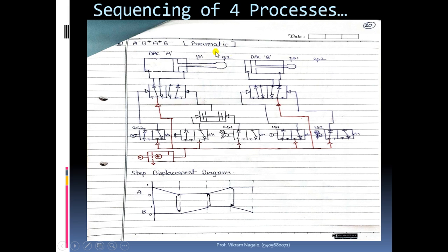That means the limit switches placed at 1s2 and 2s1 will be in press condition. Those will be initially active, as in press condition, and the limit switches placed at 1s1 and 2s2 will be unpressed. Unpressed means inactive. Inactive means the air cannot come out from those components.